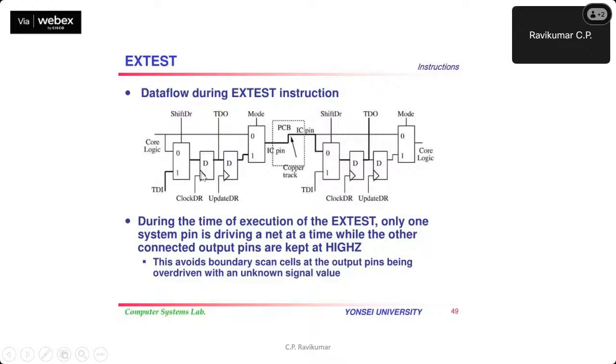And I will use the shift mode to bring in whatever data I want, right? So now I hope the reason for having the second flip flop is clear, right? So I will need to drive this guy, which I can do through this. Now the mode will be one. We will keep that data in this second flip flop.